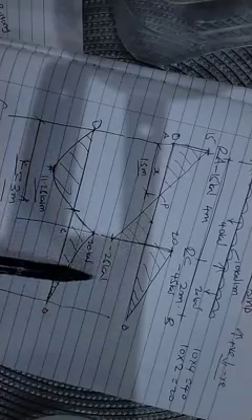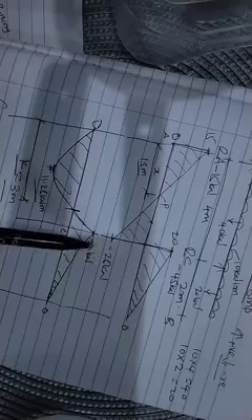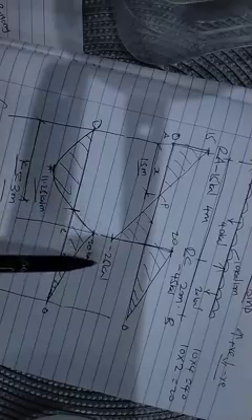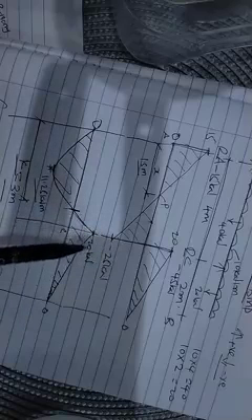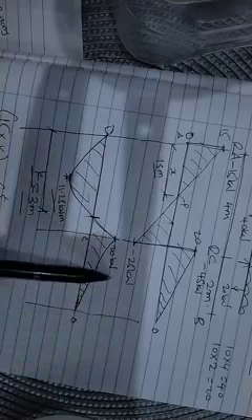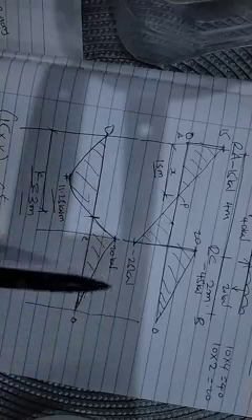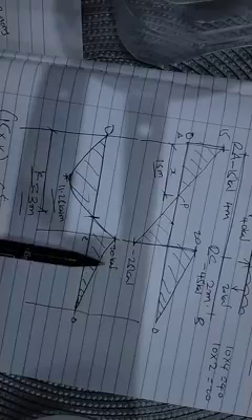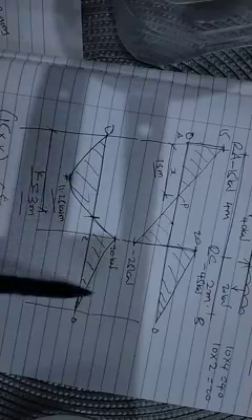So definitely your design shear force is going to be the one with the highest value. So it's going to be negative 25 kilonewtons. And then on the bending moment diagram, we have 11.25, and then we have 20 kilonewton meter. So 20 kilonewton meter is going to be your design moment, but I'm not going to proceed further to design.